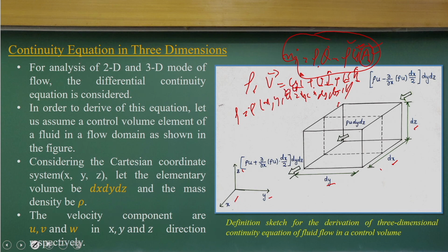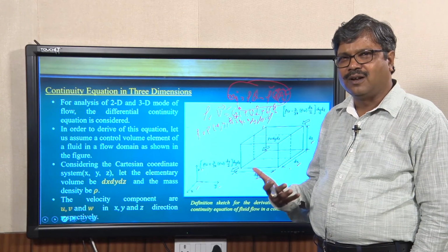So, basically, as in any fluid mechanics basics, the density and the velocity are continuous functions of space and time, and if I consider this as my control volume, I just want to find out how much mass flux is coming into the system and going out of the system. That will indicate the net change of storage of mass within the control volume, which is a basic concept, and you can go through Reynolds transport theorem for that.